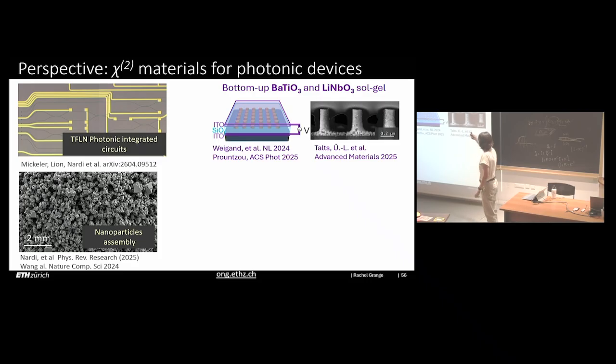And now we are going in a bit of a different direction, not using the scattering, but trying to have an easy material to structure, still transparent, but still electro-optic and also nonlinear, so that we can really exploit all the properties on a chip for having integration of Chi2 material without having, let's say, the burden to etch and get into trouble for the fabrication of the thin film.